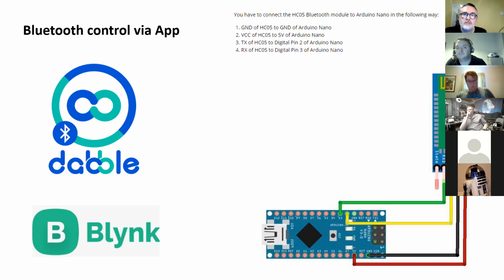All you really need is this screenshot, which shows how you connect the Bluetooth receiver to an Arduino Nano. You've got a Bluetooth board and an Arduino. If we look at how it's connected, we've got 5 volts and ground, which is powering that external board, and then there's TX and RX. This is called serial data, just a way of swapping data. The TX is connected to pin 2, and the RX is connected to pin 3. That means you've got a Bluetooth board connected to the Arduino.